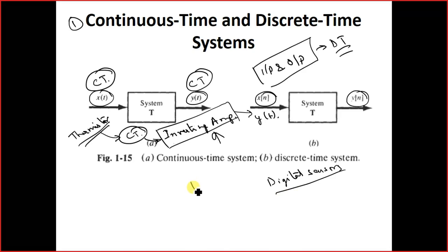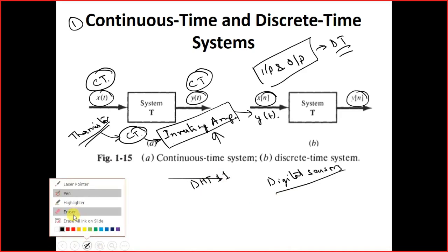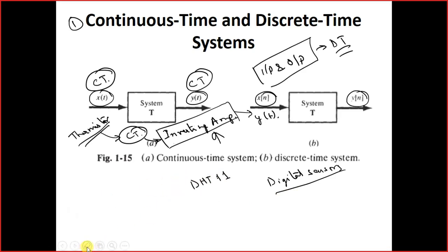One of the common examples is the DHT11. Even we can have the DHT22. These are digital sensors, and they are dual sensing sensors. That means they measure the relative humidity plus the temperature.